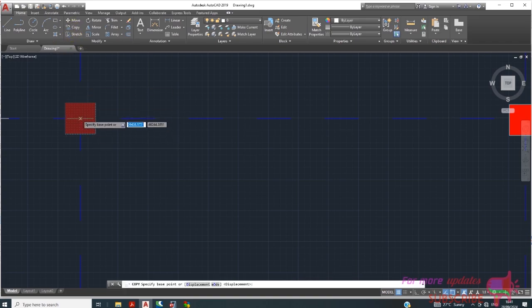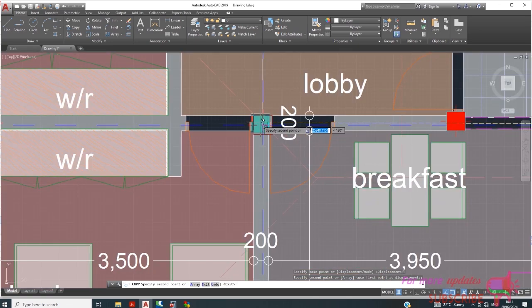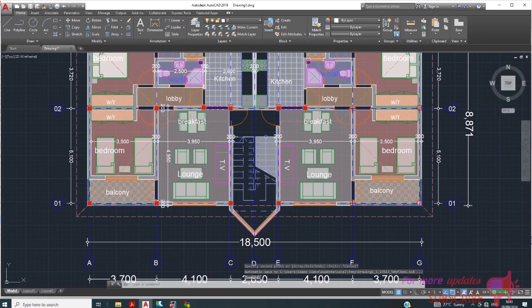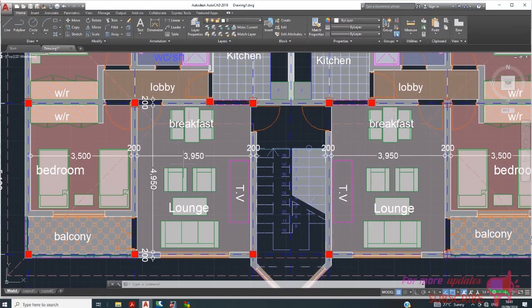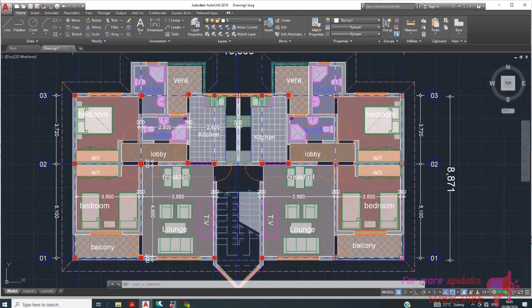I also have a beam. Copy. Let me just finish doing this. Don't ignore anything. So I will also need a beam here. A beam here. This slab is very critical. It's the biggest, largest panel. So I'm having those columns, and also I will need a beam. So this can be a partition wall, but I'll need a beam here, right? Maybe here we can add a secondary beam to support that partition wall.